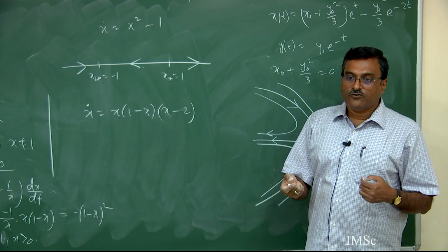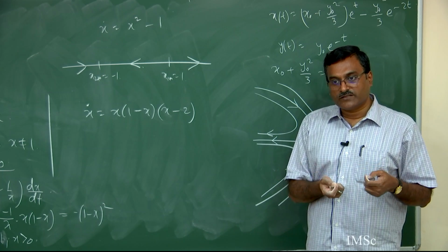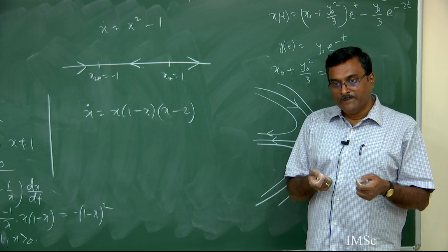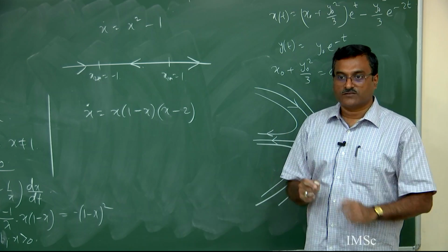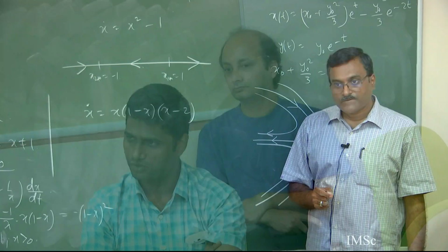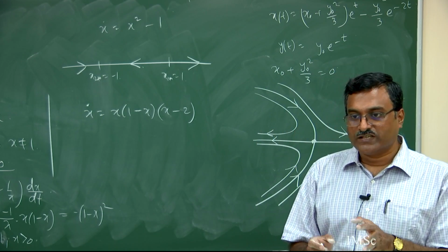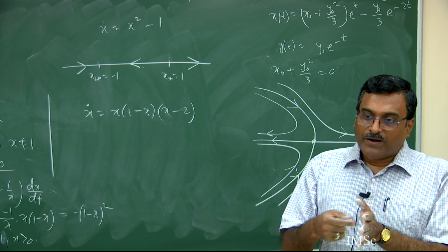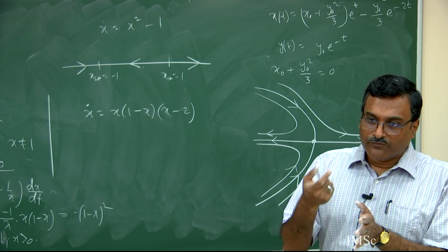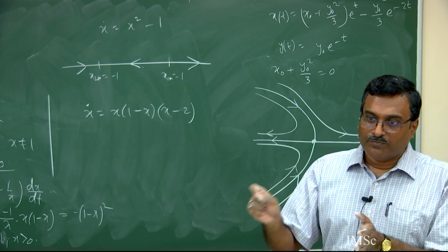then it will be quite difficult to find the roots explicitly, but there is one criterion called the Routh-Hurwitz criterion, by which you can judge the stability by looking at the coefficients involved in the characteristic equation for a 3 cross 3 matrix. It involves some algorithm like that. That is somehow related to the eigenvalue problems, but for local stability analysis, the Routh-Hurwitz criterion is the most general, because you can give a general condition for an n cross n matrix, and depending upon your problem, whether it is n equal to 4 or 5 or 6, just by looking at the coefficients of the characteristic equation, you can judge whether the equilibrium point is stable or not.